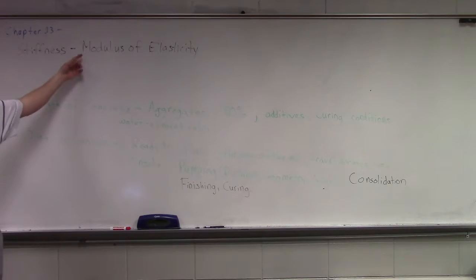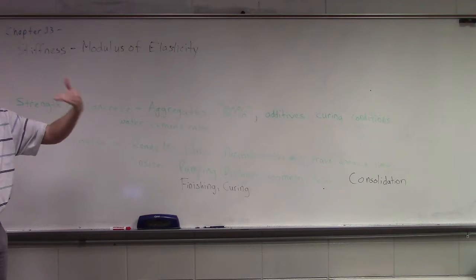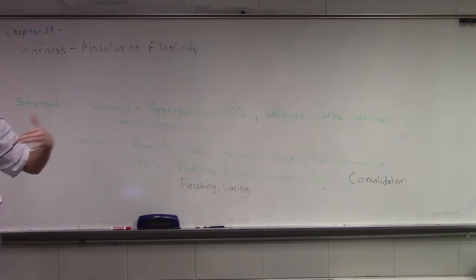Down in Florida, they exceeded that modulus of elasticity. They got out of the elastic zone into the inelastic zone. The concrete was not able to recover. Very tragically it ended up in failure where people died, okay? So it's something that we're really interested in.